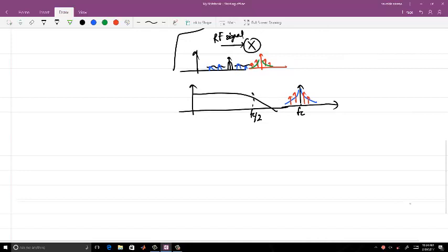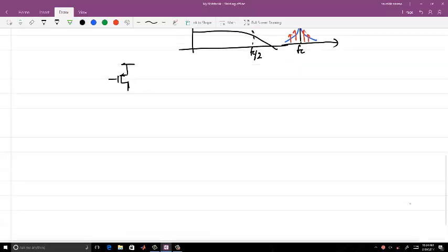If I do not want to switch a current source, I have a fixed current source, both top and bottom. So I can put the PMOS at the bottom. Okay. So VBP, VBN, and this one is ground. And now I want to switch the current.